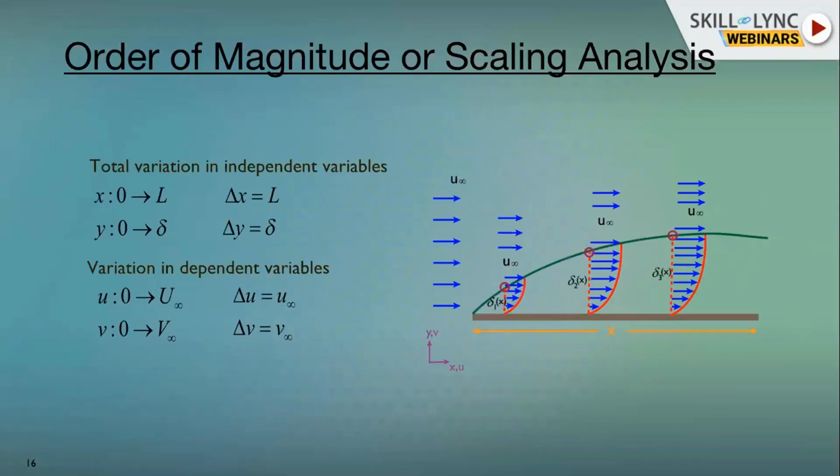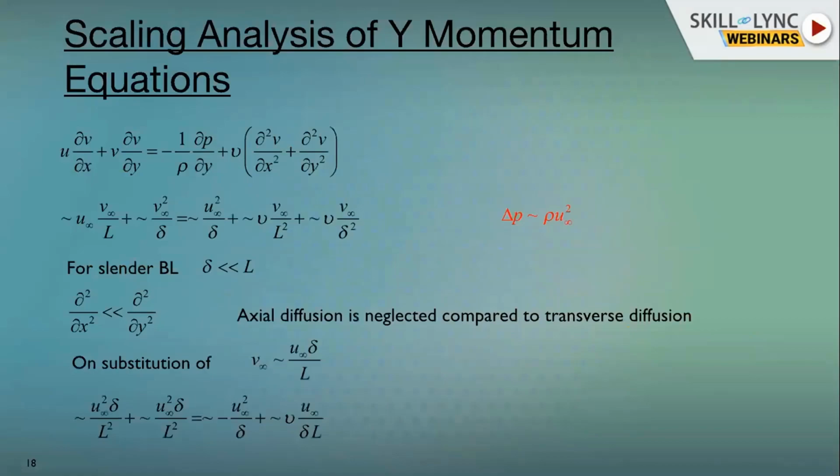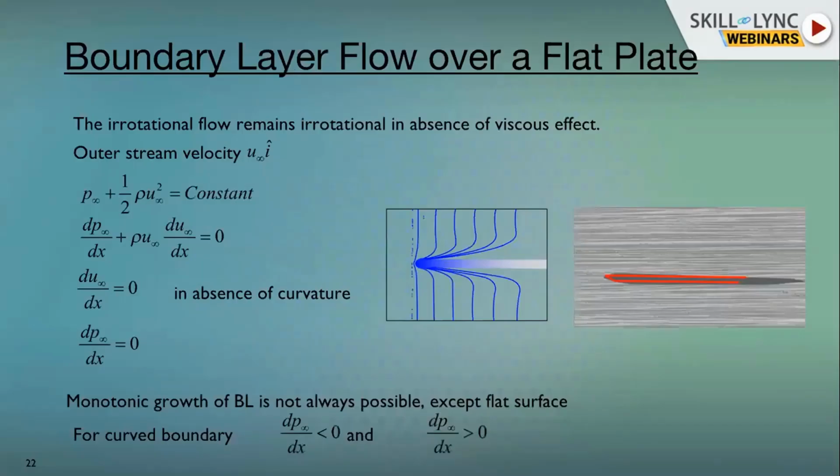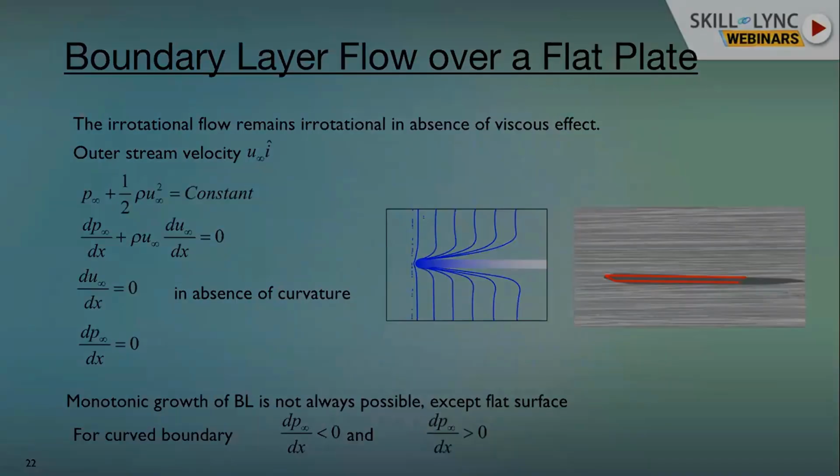Okay, because Reynolds number I know, u infinity I know, nu I know for the fluid. If I know the distance from the beginning, I can calculate the drag force. Imagine it's an aerodynamic wing and the flow is hitting over it at a different position. The aerodynamic drag force is going to be different. If you know the position, now you can calculate the skin friction coefficient and aerodynamic drag by just integrating the skin friction over the entire surface, right? So that was the finding.